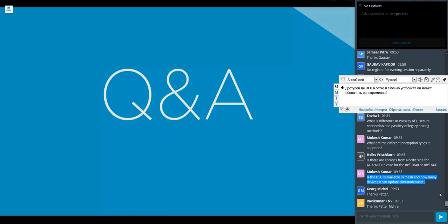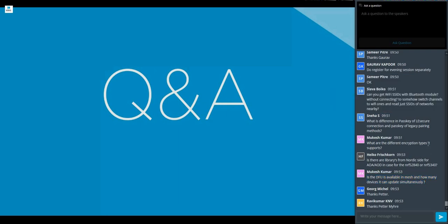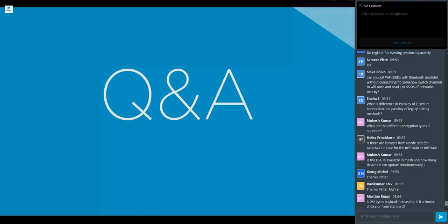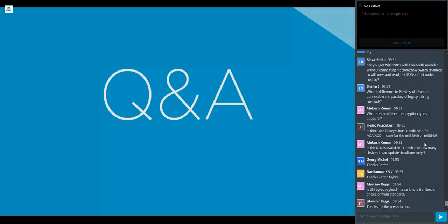Is there a way to hide the nRF BLE advertising name so that it is not visible to casual BLE users from connecting, and only my central devices? So you can identify your device with something other than a name in the advertising packet, for example, by using a unique 128-bit UID. There are also some features that if you have bonded, you can have a random address, and you can have only your central device recognize your peripheral.